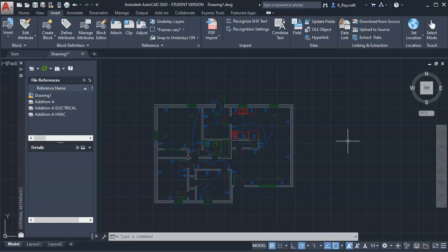And one of the primary reasons why this is important is because somebody could be working on the electrical, which would have maybe the floor plan externally referenced in, and then they want to, well, let's just say there's a potential there for circular referencing, something inserted into something else, then that something else is inserted into the current drawing. AutoCAD doesn't like that. So if that's going to be a situation that you need to concern yourself with, then it's definitely a point when you need to change that particular part of that external reference. And that is how external references work.